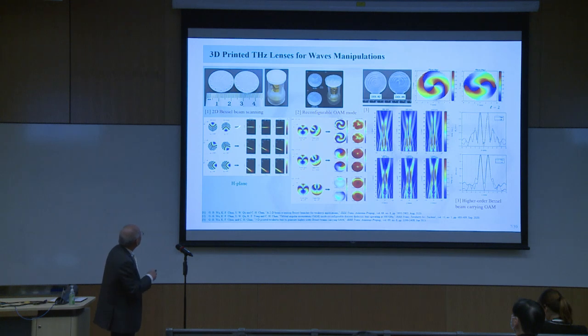As opposed to some far-field lens, where the energy will be rapidly decreasing due to the inverse square law. And this one can generate different OAM modes, orbital angular momentum. That means we can have more information from the target if we make use of these kinds of lenses. And in this particular one, we can combine the two features here to generate a Bessel beam with a different orbital angular momentum index, so that we can also change the range over which the field remains basically constant.